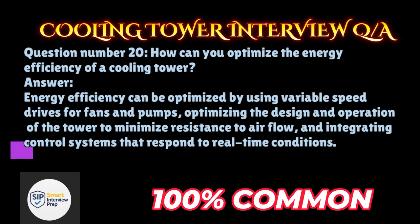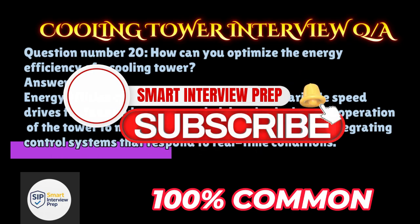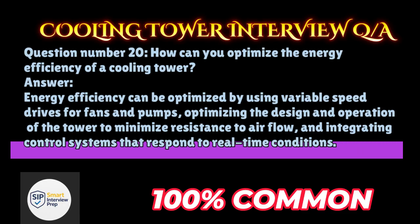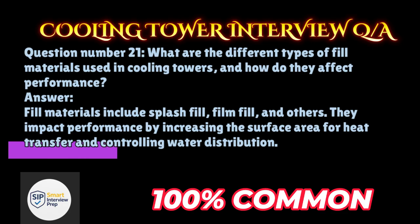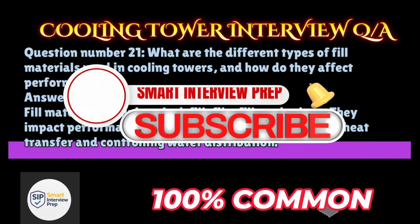Question number 20. How can you optimize the energy efficiency of a cooling tower? Answer. Energy efficiency can be optimized by using variable speed drives for fans and pumps, optimizing the design and operation of the tower to minimize resistance to airflow, and integrating control systems that respond to real-time conditions. Question number 21. What are the different types of fill materials used in cooling towers, and how do they affect performance? Answer. Fill materials include splash fill, film fill, and others. They impact performance by increasing the surface area for heat transfer and controlling water distribution.